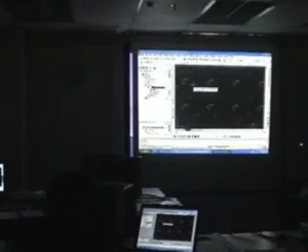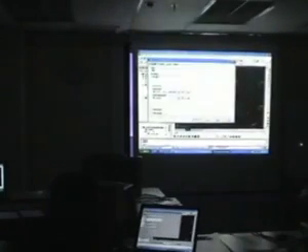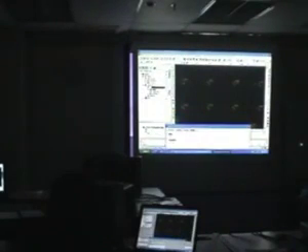So this is very different from Land Desktop. In Land Desktop, you have to create all this yourself as you move along. With Civil 3D, you just set the settings and modify, and say, okay, instead of seeing the slope arrows, I want to see the points, and you just apply. It will update for you. So it's lighter in the sense that you don't have to load them into the drawing.